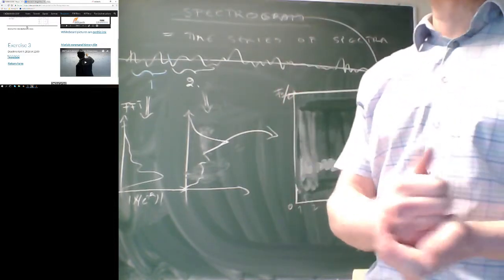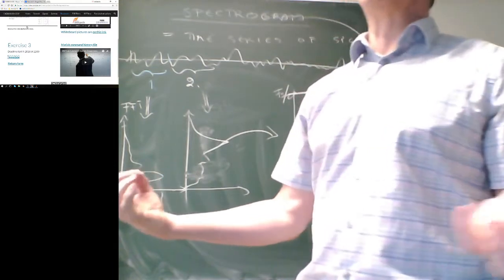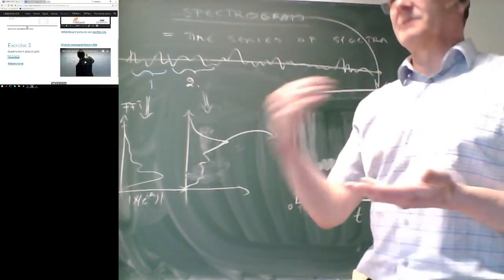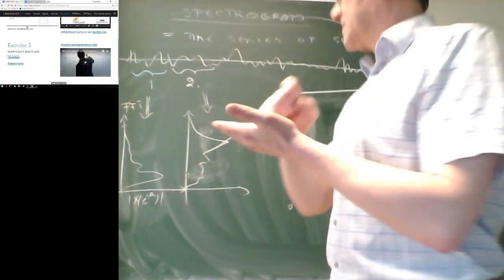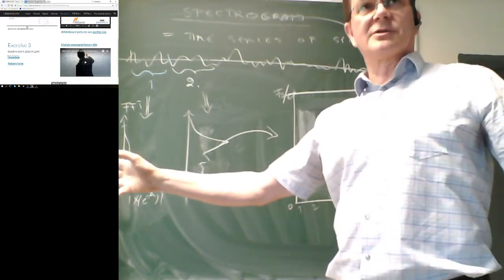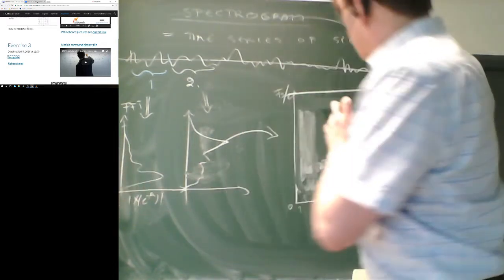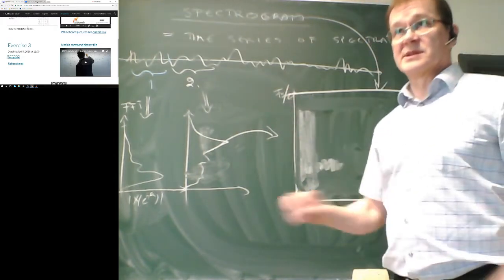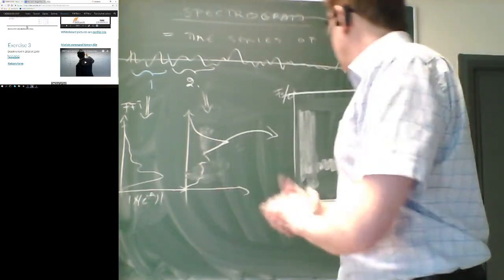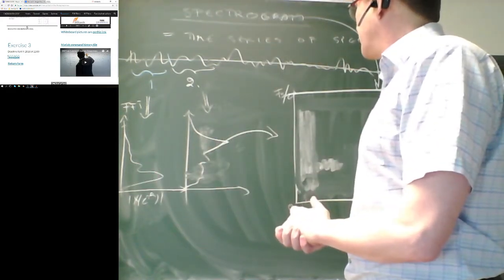On the time base you cannot really do it, since voice samples are very random. If I try to speak exactly the same words time after time, they still do not correlate in the time domain, because there are still some small changes, and even a tiny change at the beginning will make the correlation evaporate. But on the spectral plane, you can start correlating the spectral images, and that is a totally different thing. Good. All right.